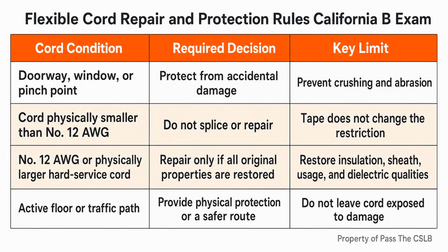The general building contractor's field role is to recognize when the basic support does not even meet that starting point, and to coordinate correction by the responsible trade. Portable generators have a narrow frame grounding exception. The generator frame does not require a separate grounding electrode when the generator supplies only equipment mounted on the generator and cord and plug connected equipment through receptacles bonded to the frame.